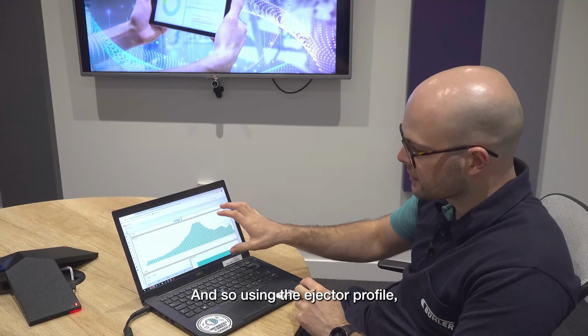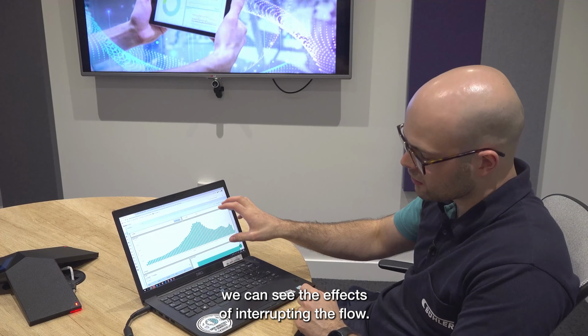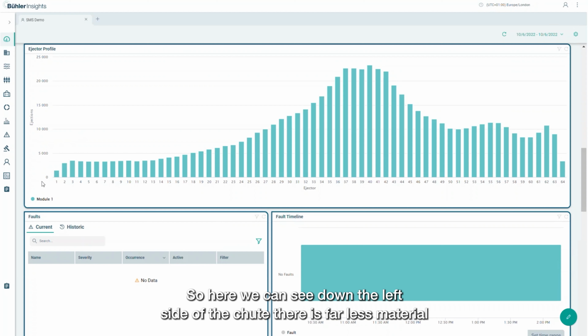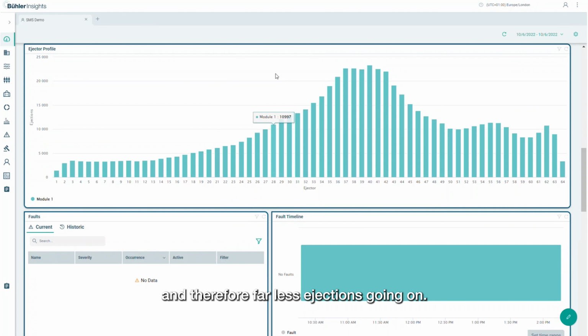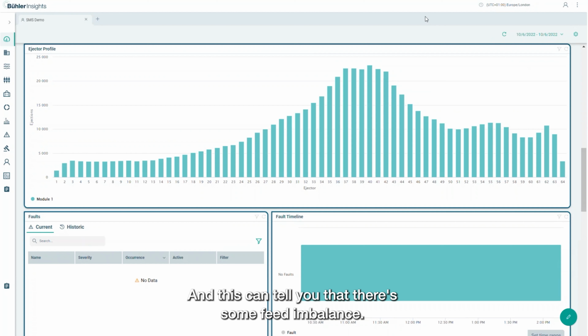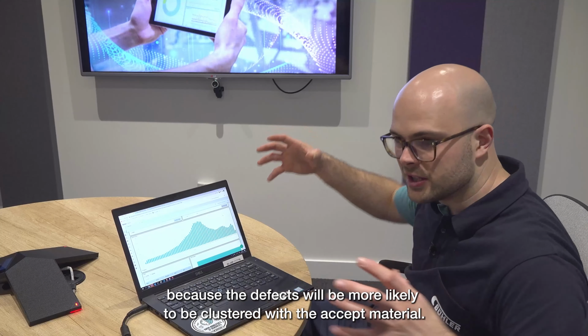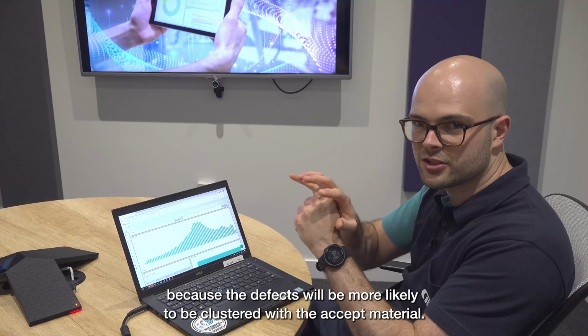And so using the ejector profile, we can see the effect of our interrupting the flow. Here we can see down the left side of the chute there's far less material and therefore far less ejections going on, and this can tell you that there's some feed imbalance. Due to this feed imbalance, you'll have a higher rejection ratio because the defects will be more likely to be clustered with the accept material.